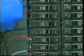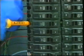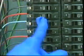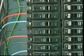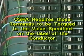Conductors of dissimilar material should never be intermixed in terminal or splicing connectors, where physical contact occurs between the dissimilar conductors. OSHA requires those terminals to be torqued to the value specified on the label of the conductor.